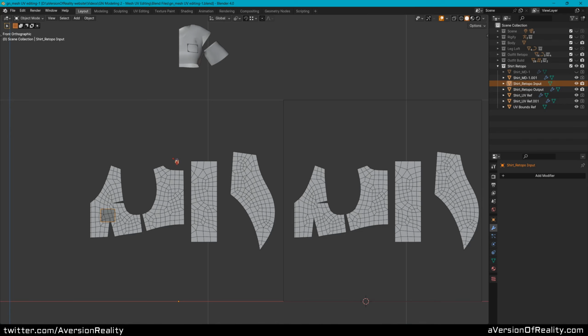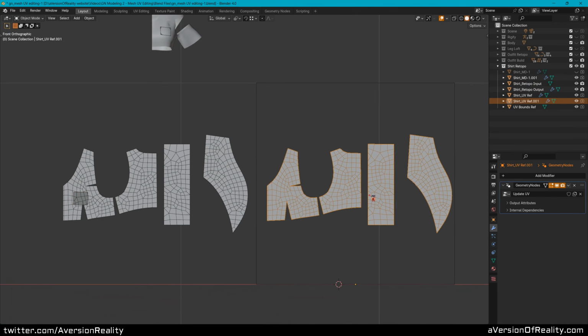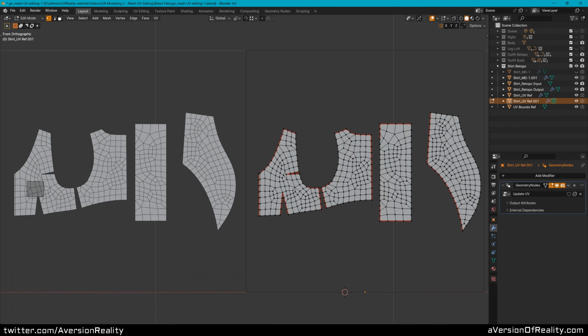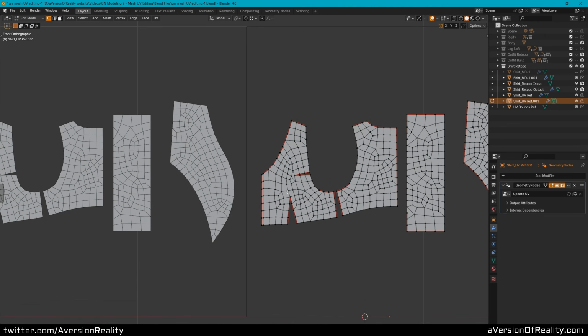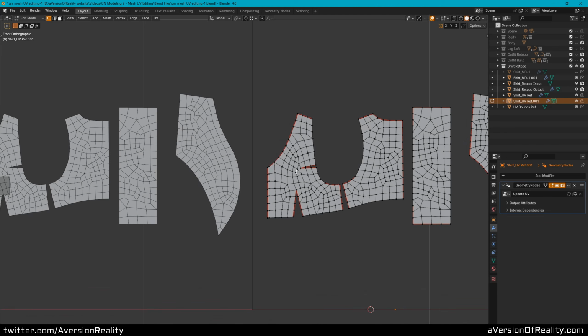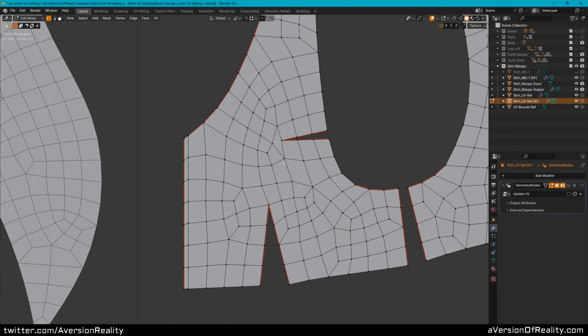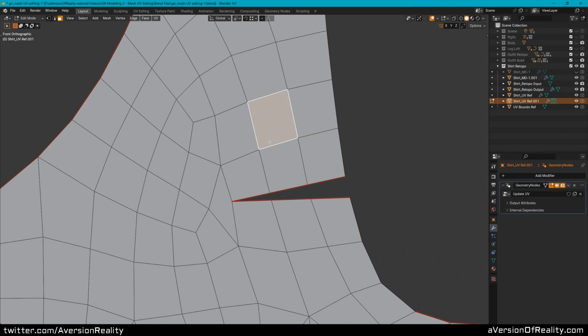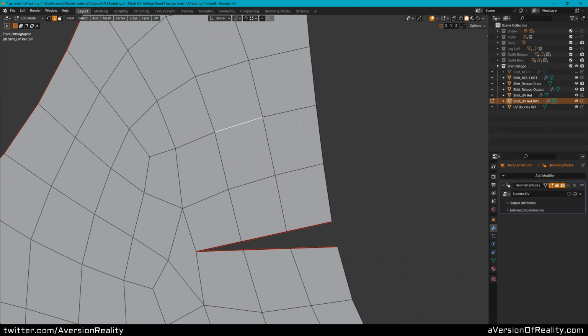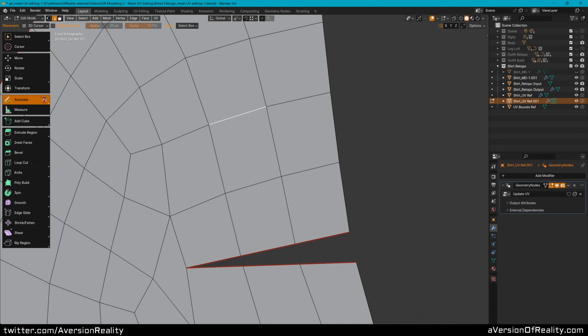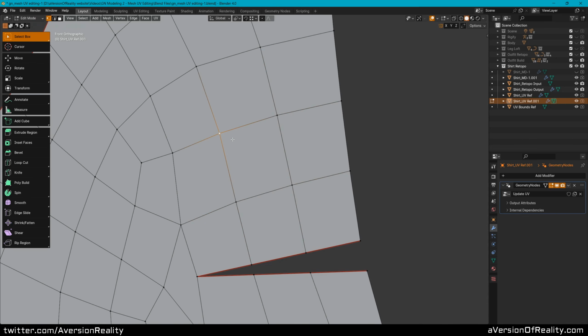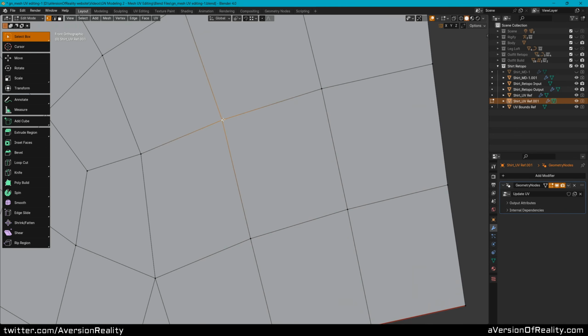So keep in mind that we are working with a giant restriction here. Anything we do has to not change the number of face corners in this mesh. You may be wondering, what is a face corner? Well, you know what a vertex is, and you know what a face is, and you know what an edge is. Face corners are the secret hidden fourth data domain. Every face has a corner for each vertex, so a quad like this has 4 corners. Basically, face corners are what allow you to have different data on different sides of an edge. They allow split meshes.